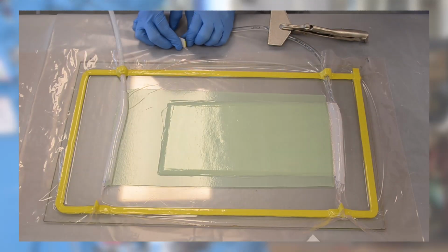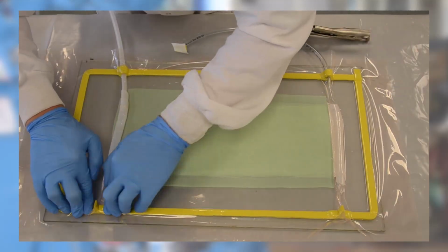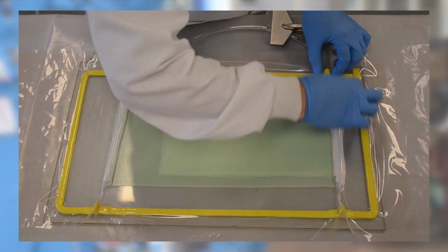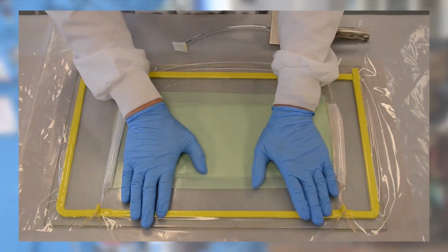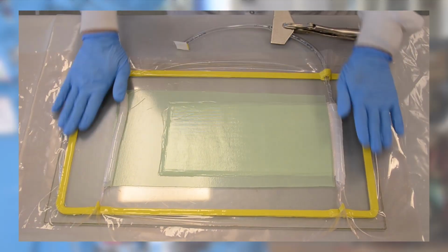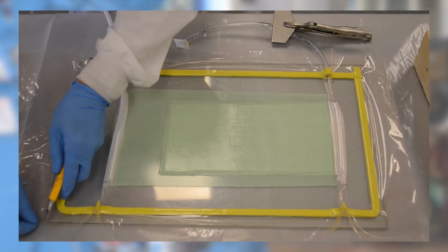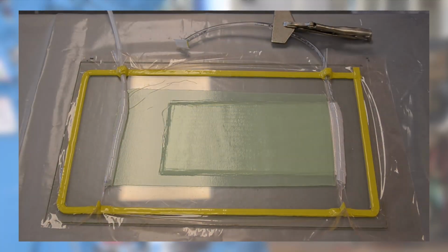Another source of experimental error is from air leaks in the vacuum bag. If the vacuum bag is not airtight, the vacuum pressure on the resin will not work as intended. Resin can leak out of the bag too. If the leaks are big enough, the entire process can be compromised. These leaks also make it difficult to measure permeability as the flow front speed is varied.